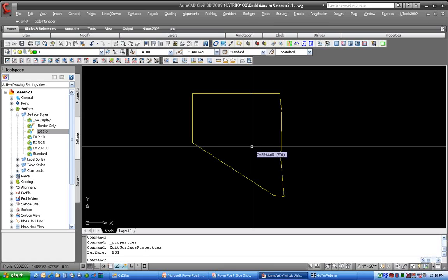This is the best way to store surface model drawings because it reduces the file size to a minimum. Okay, the surface is still there. I can still get elevations. You'll see I have a tooltip on my screen showing me the Z value for that surface, but the file size is significantly smaller than if you save it displaying contours.